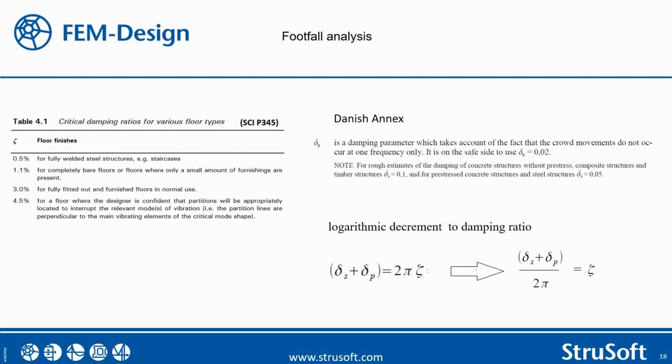In this slide, we have a recommendation for damping according to SCI P345 and the Danish Annex. Good to know, in FEM-Design, the input parameter for damping is the damping ratio. But in the Danish Annex, the damping parameter is given as a logarithmic decrement. So in the equation in the bottom right, you have an illustration of how to go from logarithmic decrement to damping ratio.